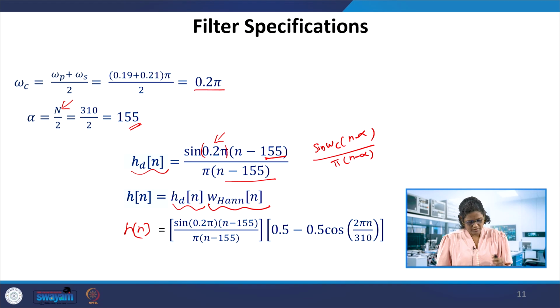If you get the coefficients, you can use them in the generalized formula and plot the response. Give the specification in the designer tool and get the coefficients and the frequency response as well. Then use these filter coefficients in our Verilog module.